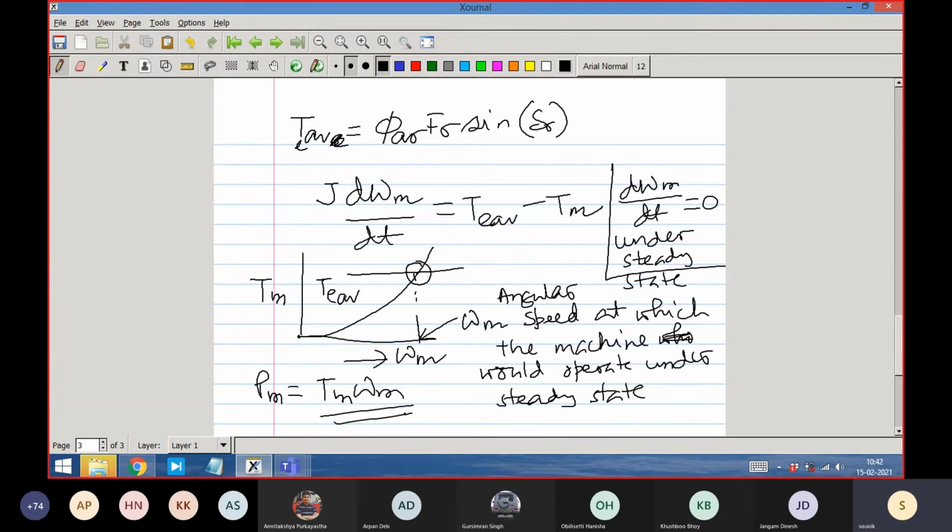There are two types of induction machine. I'll come to that, but let's forget that. Our basic point where we inject our electrical constraints is the stator, the basic terminals, in a normal application where there is no inverter. Inverter has an electronic way of injecting the voltage and the frequency that we require. But you forget that. That is inverter electronics you learn in the third year. In a conventional application, the only way we can impose electrical things is by giving a voltage. Agreed or not? Just a simple statement, do you agree or not?